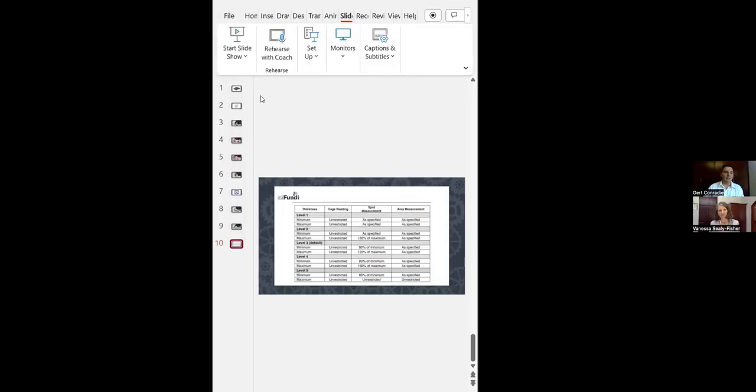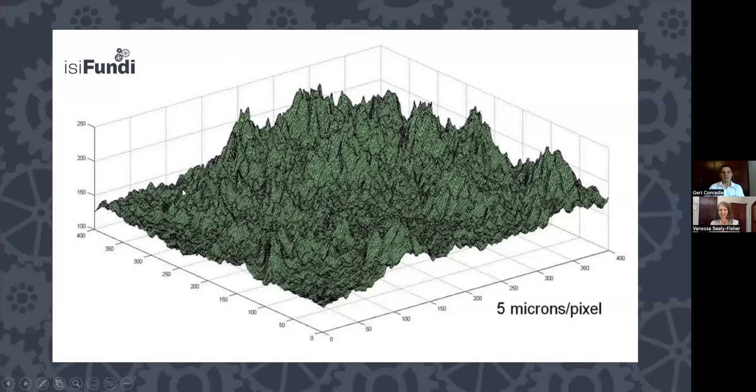Okay, that makes sense. So we've blasted the surface, and having physically felt it, you can feel whether it's very sharp or whether it's like smooth sandpaper. I'd like to share my screen with you and give you a representation of what we are looking at when we say we're looking at a blasted surface. When you look at this actual representation, it's only a 5 micron enlargement of what you're seeing on top of the surface. As somebody else who helped us with our videos and recordings said, it looks like a beautiful forest. It does.